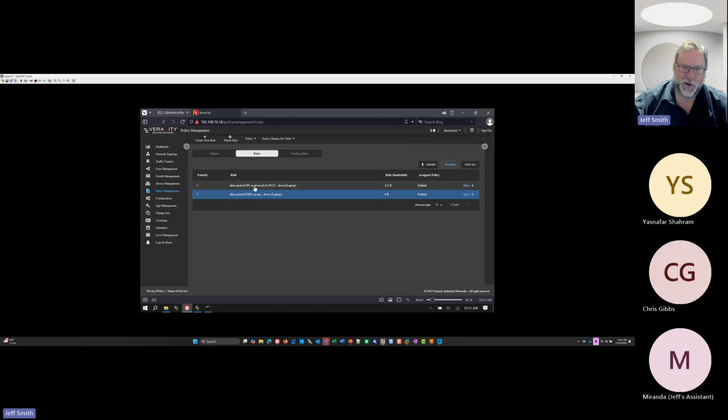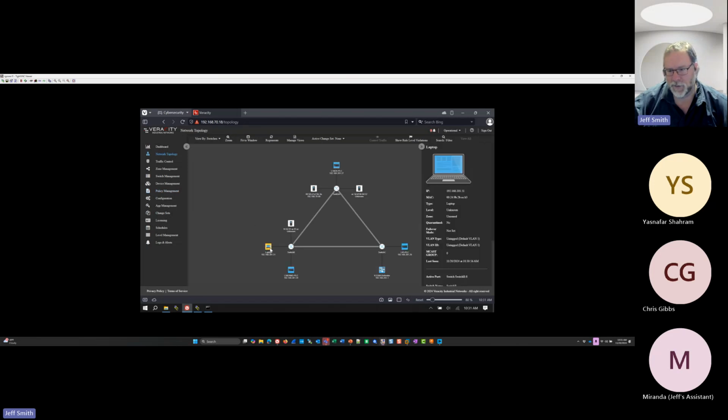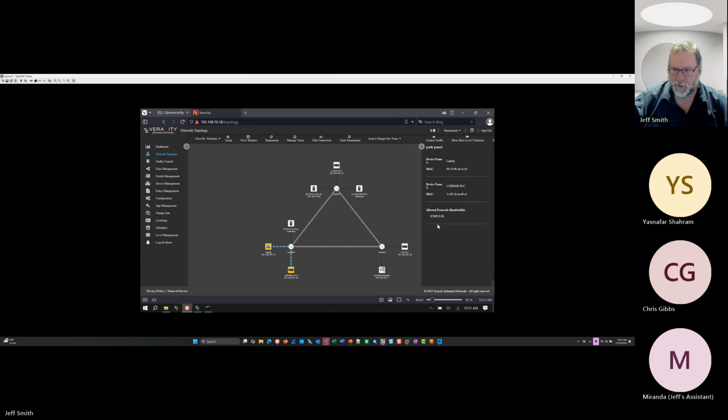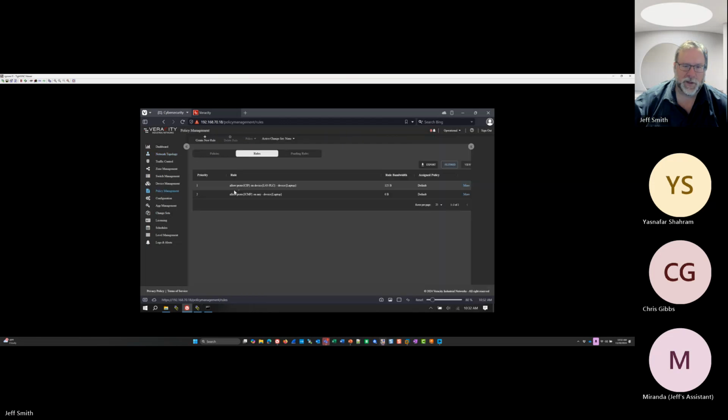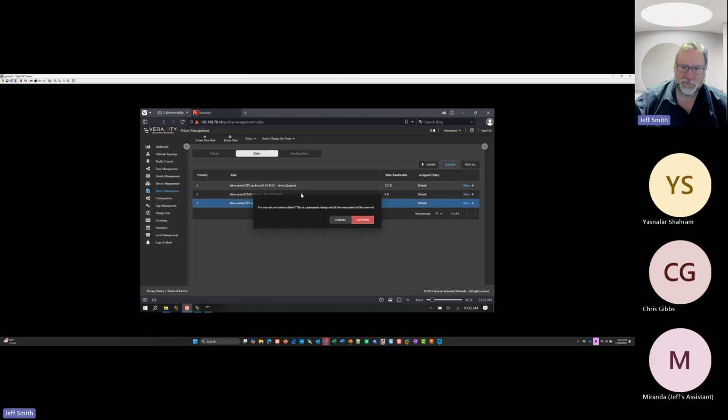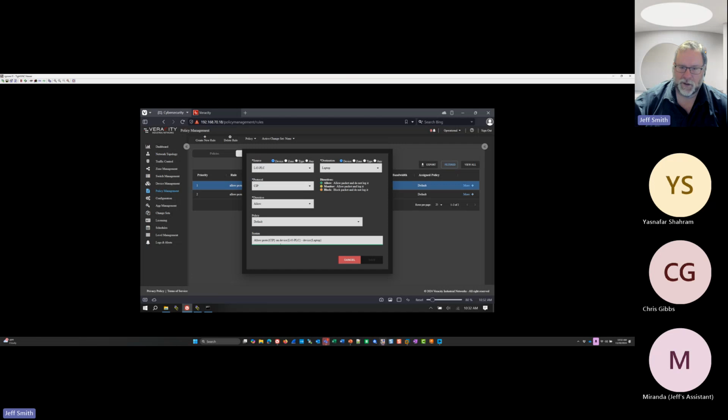Kind of the same way where here I said, allow proto SIP on device L43 PLC. If I come over here and grab my laptop and pick this guy, I can see there's no allowed protocols currently other than ICMP. I could come in here and say, allow SIP. And if I come back over to links, when it gets around to catching up, we can see that I can now browse this PLC and talk to it, but I still can't talk to him, right? I haven't allowed that. But again, I can either create another specific rule or delete this one. I'll edit this one and I'm going to allow PLC SIP on any.